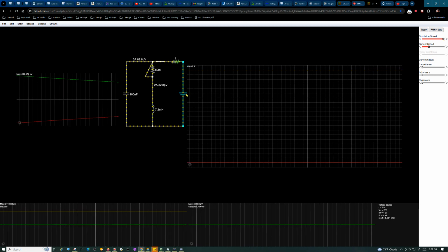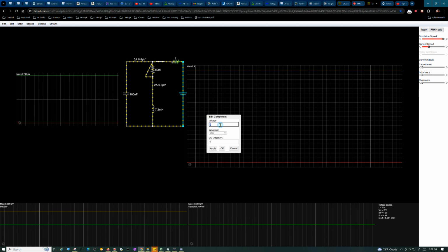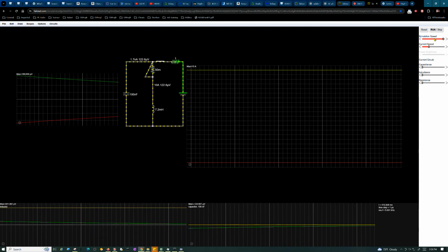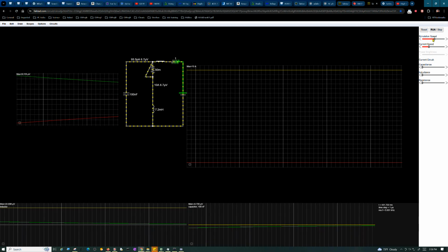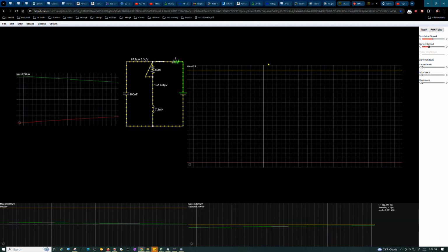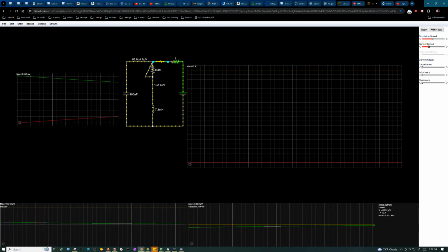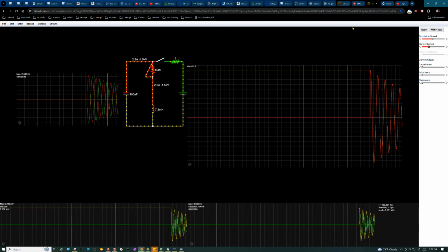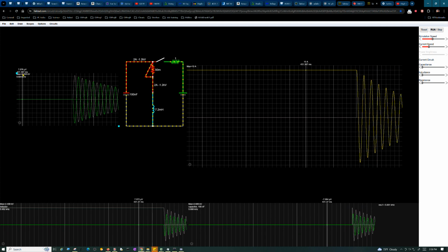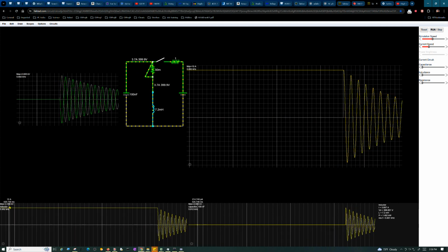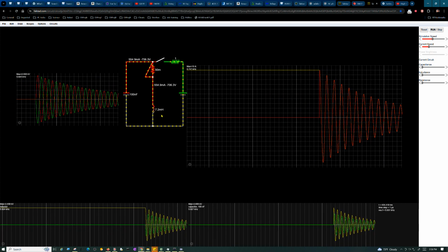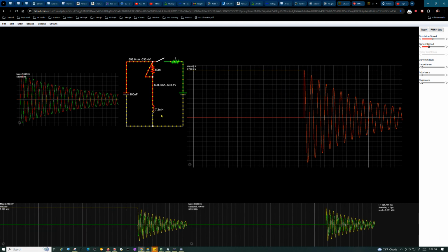Oh, remember I reduced the voltage? I forgot about that. So I had it set to 10 volts originally. So we're up there to that high current. Now let's open the switch and see what happens. Wow, 2 kilovolts, 2.4 kilovolts. That's based on the 10 amps we stored. It's about half a joule, I calculated.